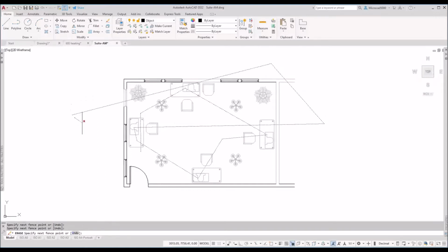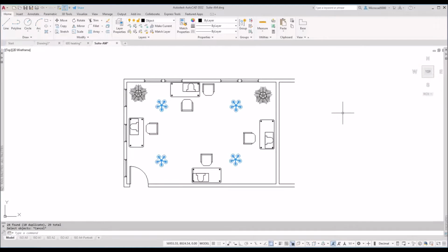That's a selection fence line. When you hit the enter key, it tells you how many it's found. So they're all the options that you've got when it says select objects: your blue boxes, your green boxes, and your lassos, and forcing it to be a blue window, a green crossing, or that fence line.